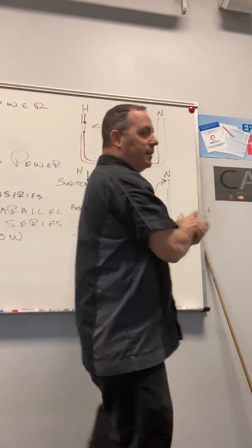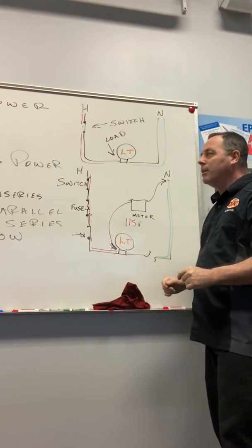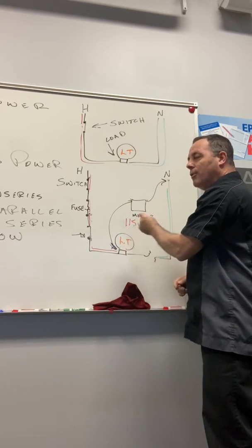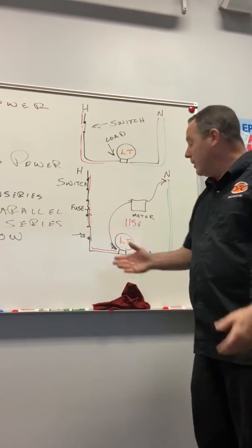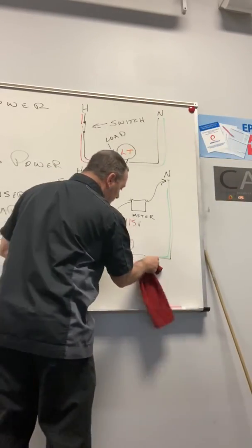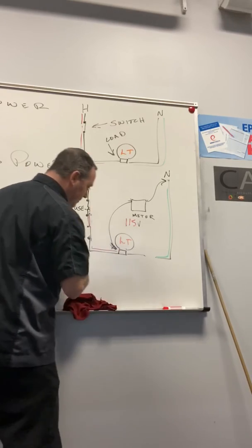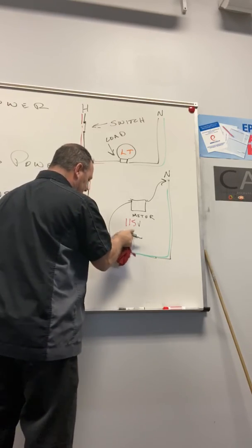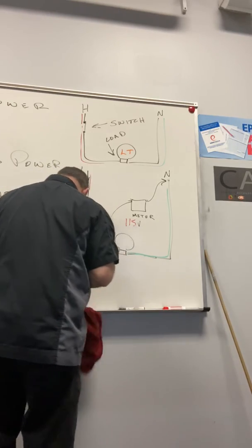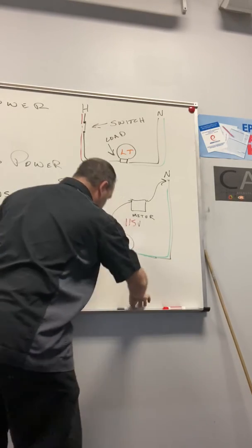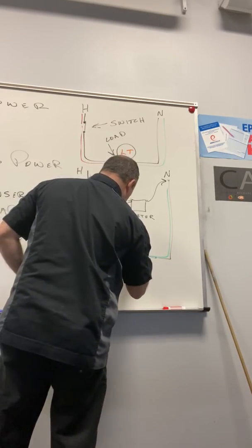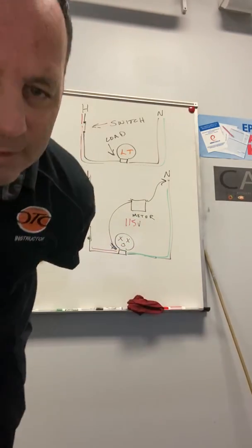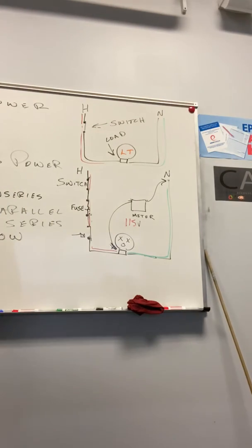So the principle said, you could say anytime I have power to my load and my load does not work, the load is bad. Because you have power to it. If you have power to it, then it should work. But let's say it's not working. Guess what? Light bulb bad. Power at the load, load's not working, it's bad.